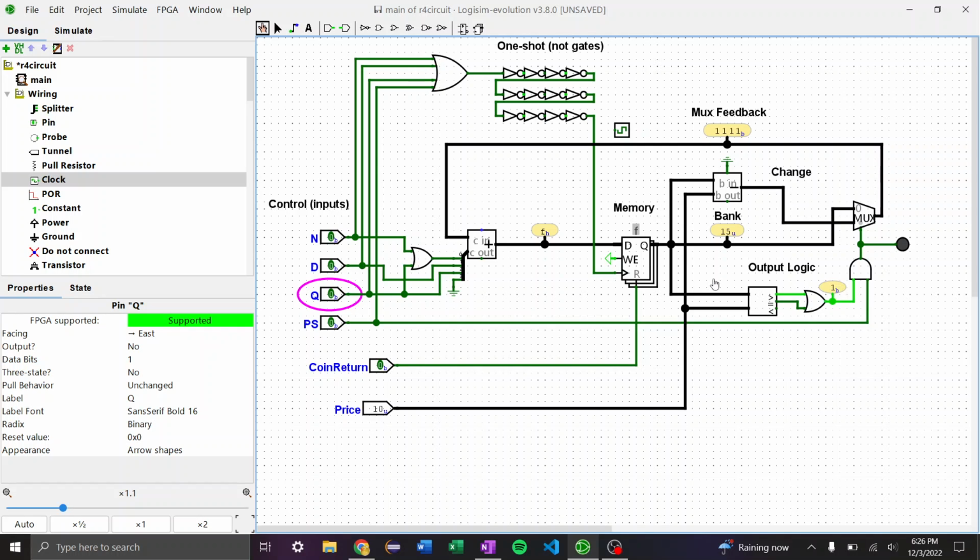And then in your circuit, temporarily disconnect the delay device. So use the NOT gates and connect it to a clock, which I will do right now on screen. So I'm going to bring this wire down here, and there's our clock. So now we do not have the delays of our NOT gates. And we have our clock on right here. And we're actually going to try a high frequency.